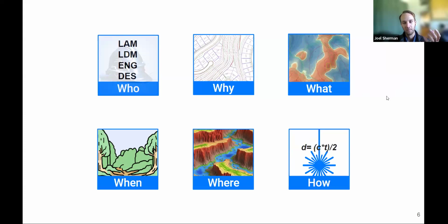And then what this is, LiDAR data, is really just the information we're using to derive an original grade profile of a site, specifically targeting the earthen surfaces and extracting that to be able to use in comparison with our design and know what kind of effort is going to be required to perform work. So we're deriving this original grade data set using a LiDAR point cloud. That's what it is.